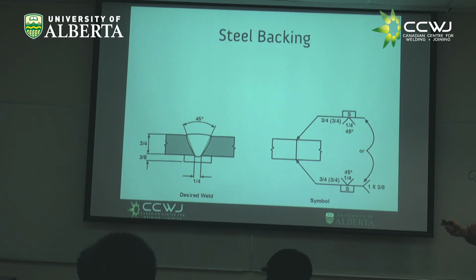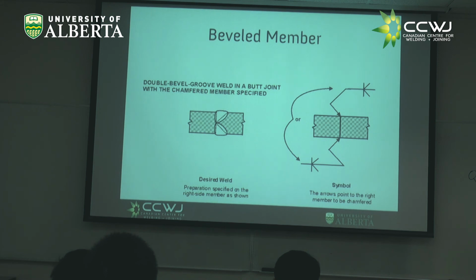Right? Okay. So here they're saying in the backing plate what size of backing plate you should have, right? 1-inch width, which they didn't put, but 3/8 in thickness. One more thing, because I think we'll need to stop soon. Two more things. One is this has a double bevel, right? It's not a V, it's a double bevel.